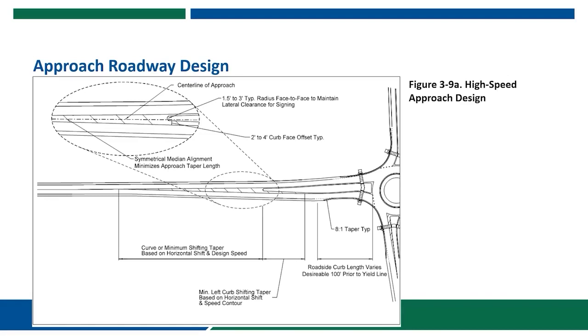Section 3.10 and appendix C of the GDOT roundabout guide include additional discussion pertaining to the super elevation for the design of the approach curves. GDOT notes the idea of the visibility package, and they prefer to ensure that the signs, pavement markings, raised pavement markers or delineators, and landscaping on the approach serve to reinforce the need for motorists to reduce speeds.